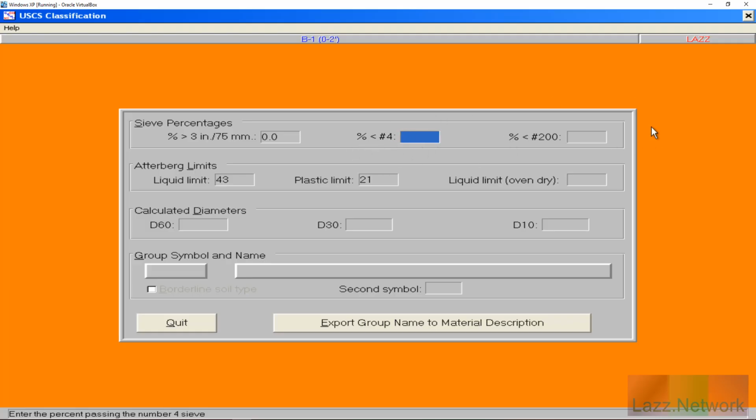So the way classification works overall in general is you have your number 4 sieve, and your number 4 sieve is your determining factor of what is rock and then what is coarse sand. Coarse sand is material that's going to pass the number 4 but is retained on your number 10 sieve. I can't remember the size openings for a number 10 off the top of my head. I think each opening's 2 millimeters, but don't hold me to that, because when it comes to sieve sizes, I'm used to the U.S. standard, which is the numbered sieves.